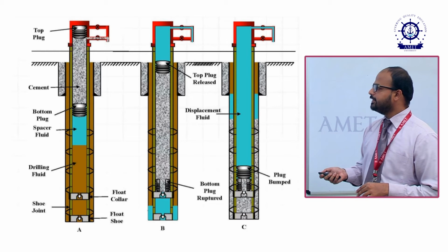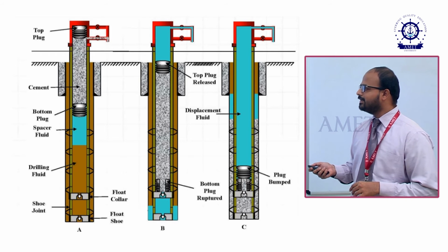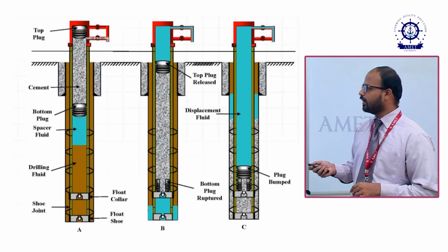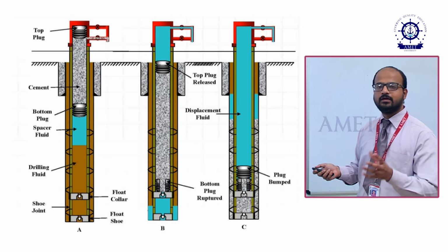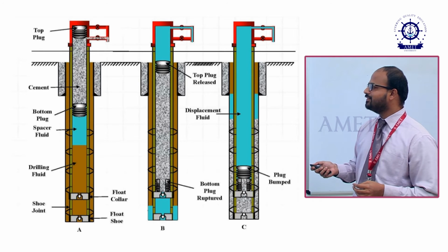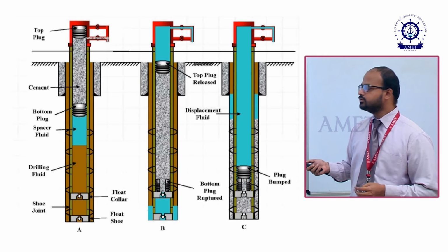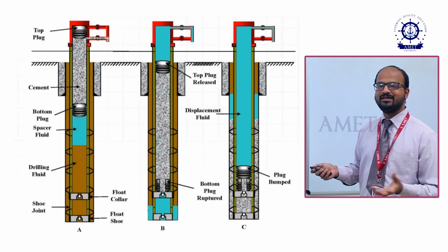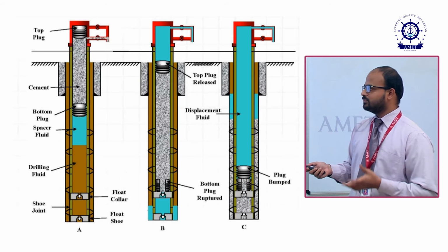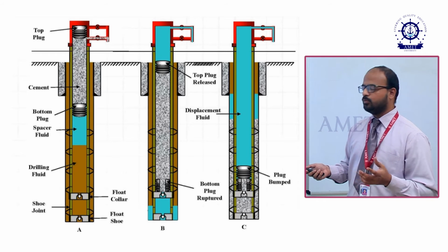Once the spacer fluid is pumped, again we have to put the bottom plug. This bottom plug contains the rupture. It simply wipes. You can see there is no brown color inside your casing pipe, which means whatever was there is completely wiped out. That's the reason we are pumping this spacer fluid as well as this bottom plug. So this bottom plug completely wipes out whatever remaining things exist. Further, it will be very helpful for the cementing. It can easily become stronger.